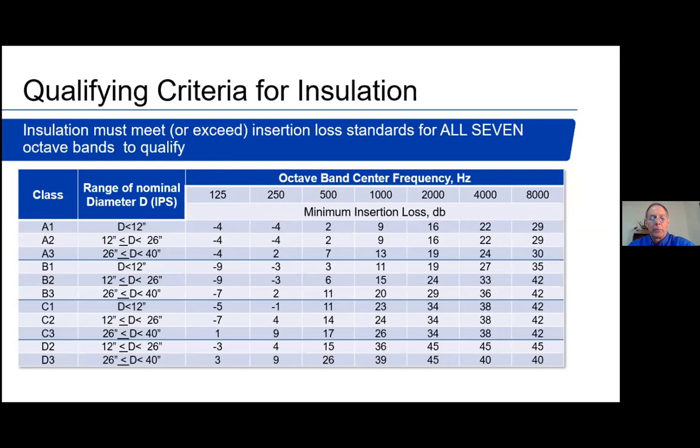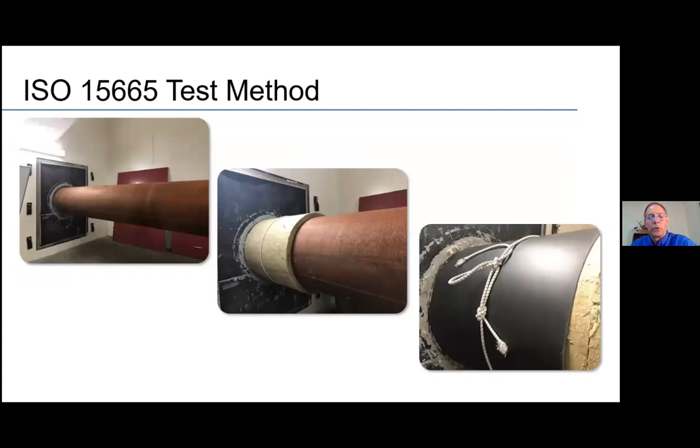And basically that comes into play as a result of the insulation system, one, creating a larger surface area, and two, the insulation system could possibly be getting excited by the low frequency vibration and noise and creating more noise than what you had without the insulation system being there. So it is real, and definitely something to keep into account when you're looking at the performance of different systems. You might reduce noise at 2000 hertz, but end up increasing noise at 125 hertz. So you need to understand if that's going to be a problem for you or not.